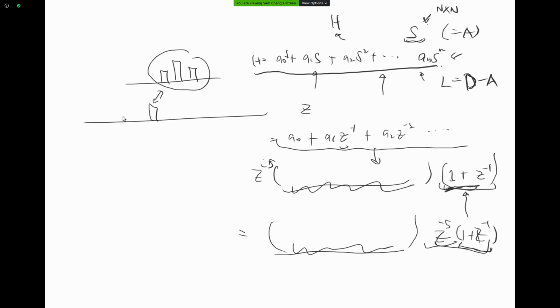It's not like if my signal is here, it has a shape like this, and if I apply it there, I have a completely different shape. That's why it's shift invariant, and that's exactly the essence of shift invariance: your filter is not going to change its profile depending on where you're applying it.